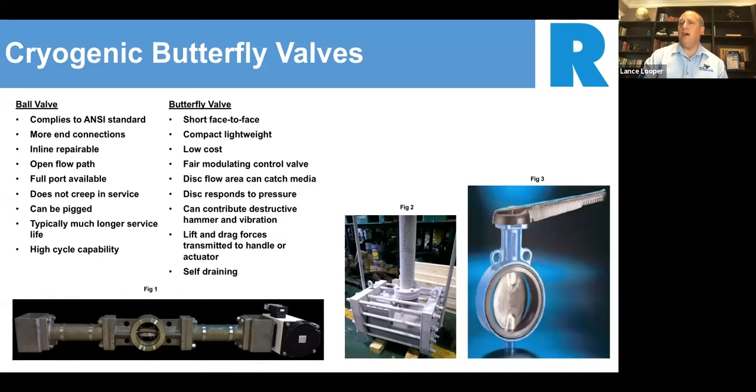You're going to get a valve that has basically a floating butterfly or floating disc in the middle, and a lot of times that can generate a lot of noise. There's a lot of turbulence that can sometimes happen, but they're usually designed to go in our air separation plants for just full flow, and we see those a lot there. We also see these on our turbo expanders. You get into some of the cryogenic plants and actually see some of the air being brought in and brought into its liquefied state. You see a lot of butterfly valves in applications very similar to that.